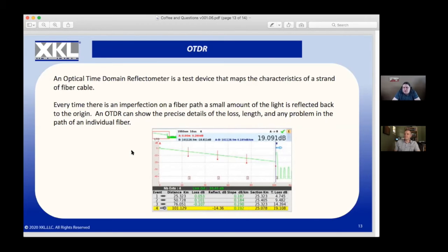With this report, you can see everything that goes on that bit of fiber and see exactly how long the fiber is, because it works by sending out a piece of light and knowing that at any point on a fiber cable where there's an issue of any sort, up to the end where the piece of glass cuts off, the light's going to reflect back at any problem, whatever it might be.